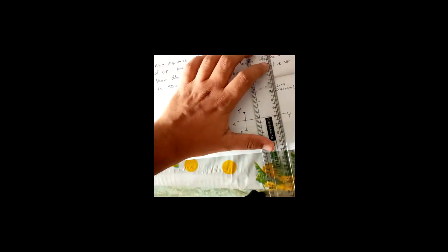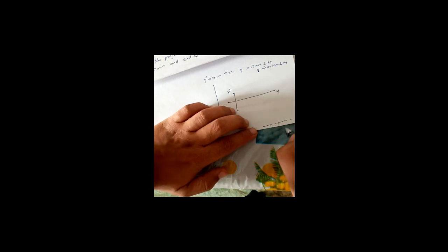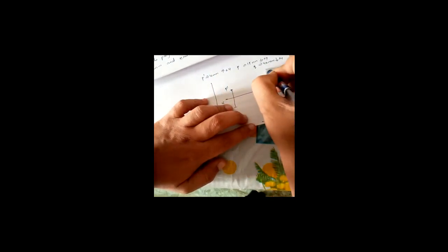So take 40 from here. So for that I will show you. From here draw a perpendicular line, on the perpendicular line measure 40 mm, that is 4 centimeter, and on that draw a line parallel to XY line. See, this is called axis line. Axis line means one larger line, smaller line, larger line, smaller line. There is 40 mm below it. So this is called the locus of Q.